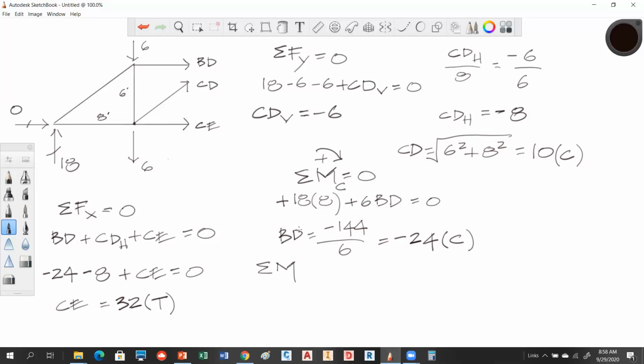So if I take a moment up here at D, okay, what I'm doing here is I'm canceling out BD and CD. I'm acting like I don't even know what they are, okay? And I'm going to resolve this, and if I don't get 32 tension, I know I did something else wrong. You guys see what I'm saying? So it's just going to be kind of a proof on the whole process. But you don't in reality, when you do these problems, have to do this, okay?